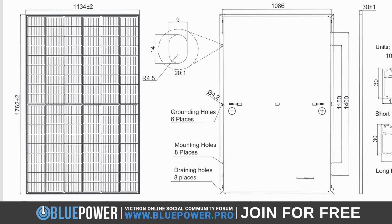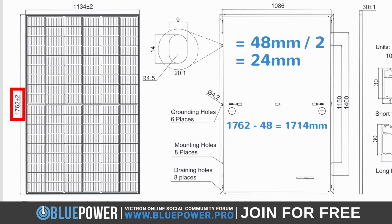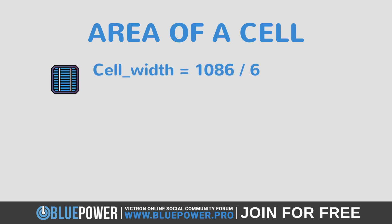Looking closer at the image provided on the spec sheet, we can see that it actually tells us the inner width, which is 1,086 millimeters. Subtracting this from the total module's width of 1,134 millimeters tells us that the total frame thickness is 48 millimeters. Then, to find the width of the frame on a single side, we simply divide this by 2, giving us 24 millimeters. As the diagram does not provide us with the inner length of the panel, we can simply subtract 48 millimeters from the provided total length of 1,762, giving us 1,714 millimeters.